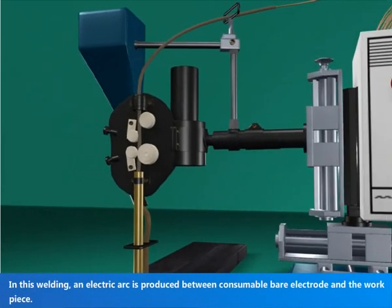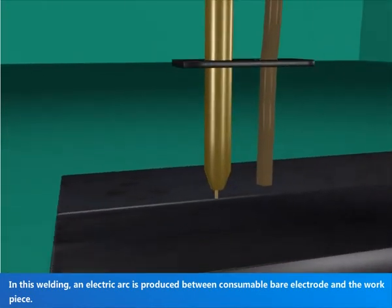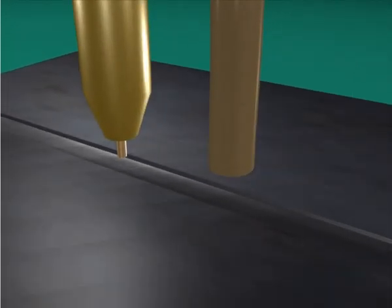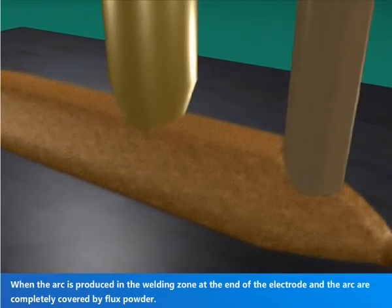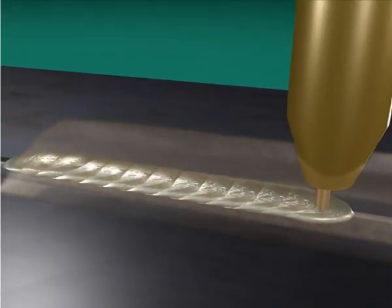In this welding, an electric arc is produced between consumable bare electrode and the workpiece. The flux powder is fed in front of the moving head. When the arc is produced in the welding zone at the end of the electrode, the arc is completely covered by flux powder.